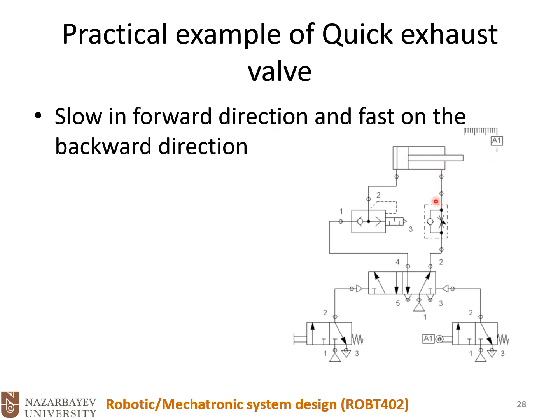However, since we have this check valve here, the speed of the forward motion is limited or controlled by this check valve. What about the backward motion? For the backward motion, this check valve does not have any effect on the airflow. We'll have the highest possible pressure here.